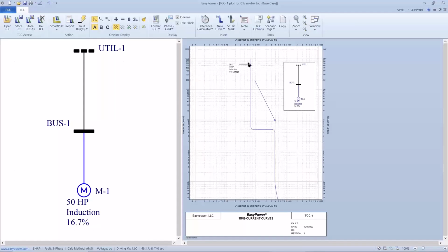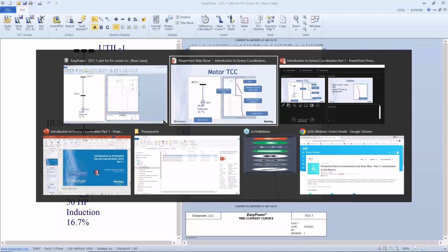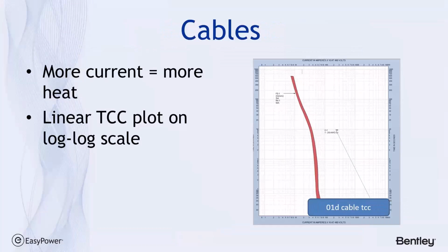and there we have the parameters that we were talking about. Again, full load current is at this level, looks like it's 60 amps, 61 amps. Locked rotor current looks like it's 388, and then the asymmetric tail potentially would bump it up to 448. Again, all this information is on the TCC, along with the thermal damage curve.